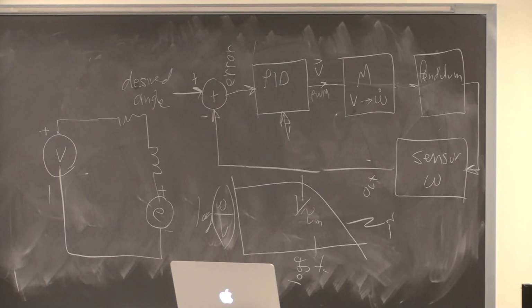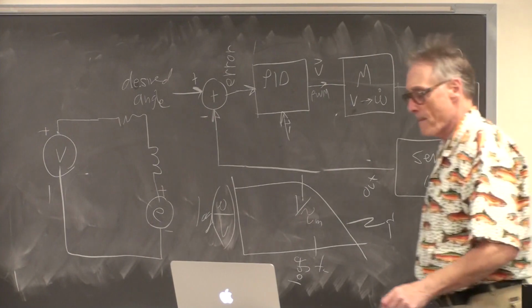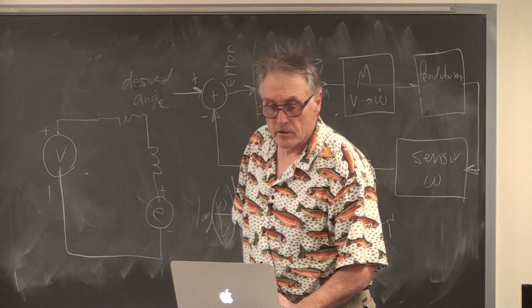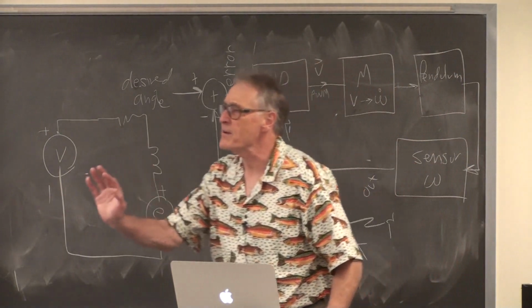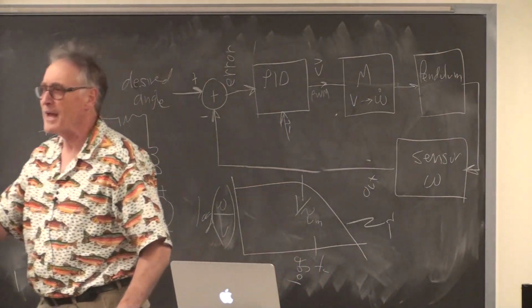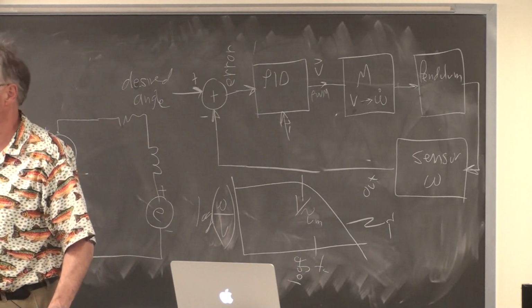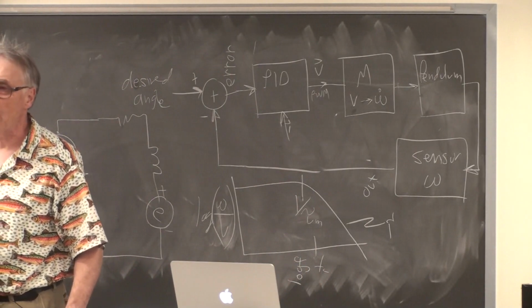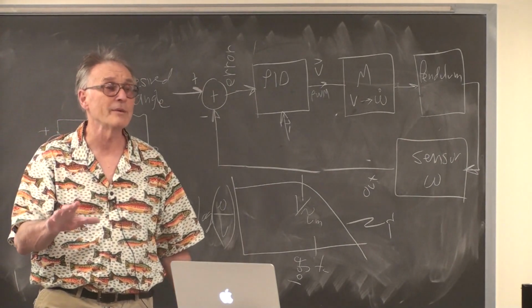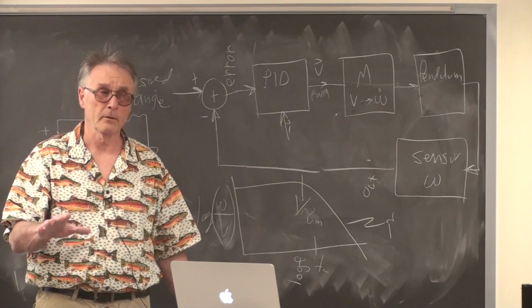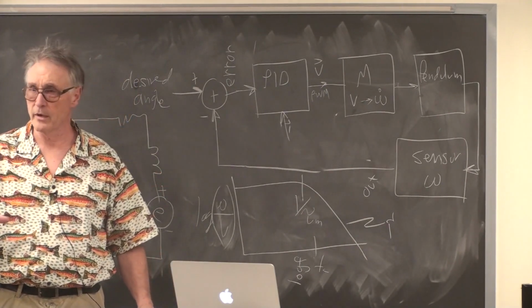Turns on, turns off. You put a square wave pulse into it. From the standpoint of the pendulum, the motor rises instantaneously. So while this matters for the response of the system, it doesn't matter very much because it's so much faster. The time constants are all dominated by the low-pass characteristic of the pendulum and the resonance of the pendulum itself. So, clear why I'm abstracting this away?